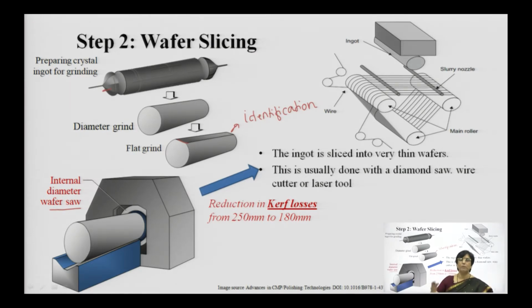You have chopping, but you have to do this very precisely, because you need a uniform surface, the substrate has to be properly flat, and therefore there is a lot of precision involved. But over a period of time, since the demand was increasing day by day, and cutting with the internal diameter saw was decreasing the yield,